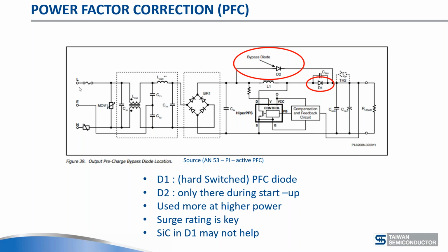So we go from the left, we see the current limiting, the fuses, the resistors, the voltage limiting, the MOV. You always use varistors on the mains, not TVS. And then you have the EMI filter, which is an important part of the application. And then you come to the bridge rectifier, which is of course where we are interested. And then in the case of power factor correction, this capacitor is actually just there for high frequency reasons and filters out the EMI. So the main storage capacitor is after the wave shaping section.